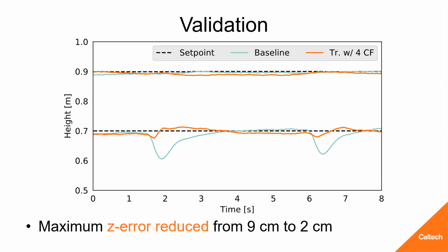The velocity is numerically estimated. Okay. And then, this is very technical, but do you actually have a Wi-Fi connection to these little things, or how do you send the information to the controllers on board? Yeah, that's very technical, but basically those little things use a similar radio as your wireless keyboard or remote would use. And there's broadcasting possible. So we broadcast the data out, and then every drone receives the position information of everyone. And then they can just filter who's the neighbor, who is myself. Yeah. Cool.